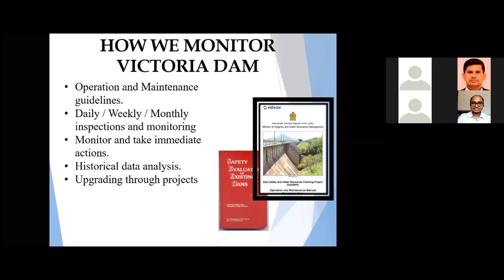How do we monitor the Victoria Dam? Actually, we have specific guidelines for monitoring purposes. As you can see in this figure, we have operation and maintenance manuals, and we refer to safety and evaluation books available, inspection reports we are preparing, and also data analysis. Through projects, we are from time to time upgrading our instrumentation and monitoring systems. I will show you later in my presentation how we have done our upgrades.